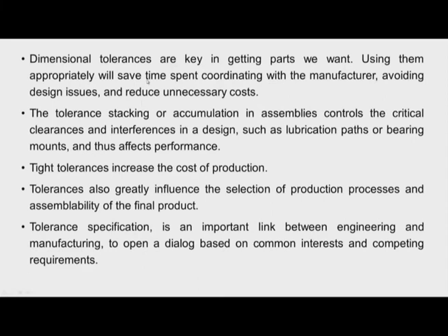So the dimensional tolerances are key in getting parts that we require, and using them appropriately will save time spent coordinating with the manufacturer, avoid design issues and reduce unnecessary costs. And tolerance stacking or accumulation in assemblies controls the critical clearances and interferences in a design, such as lubrication paths or bearing mounts, and thus the performance is affected.